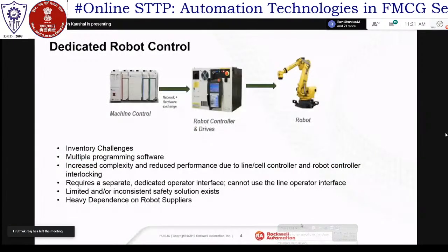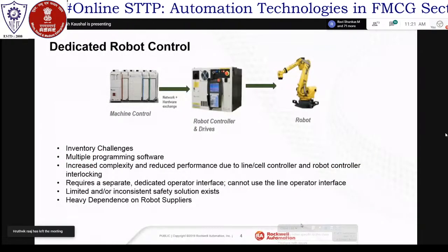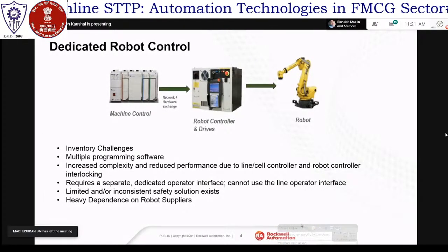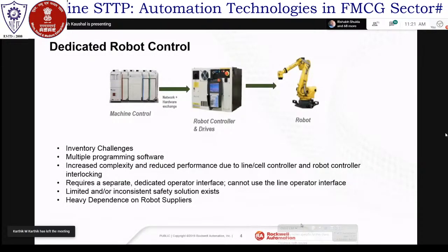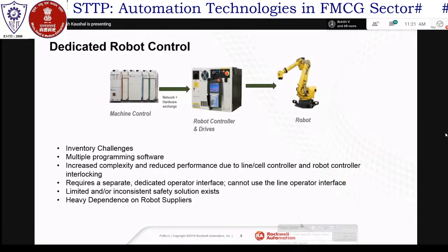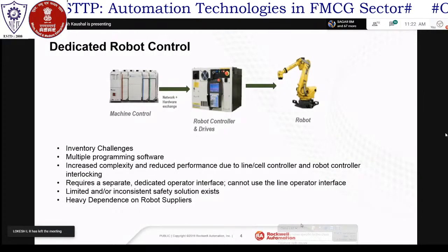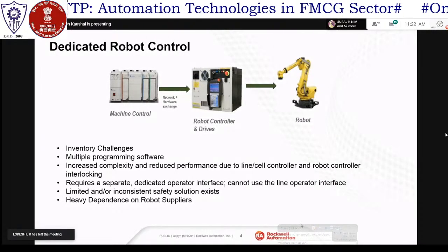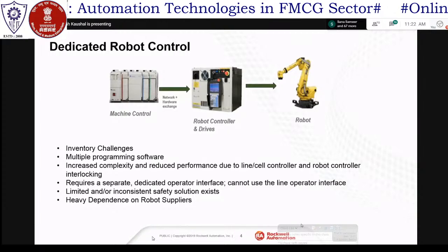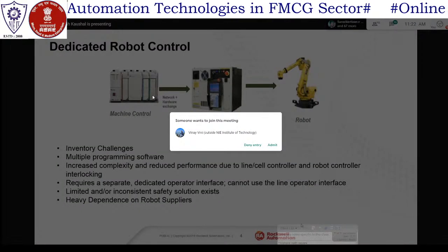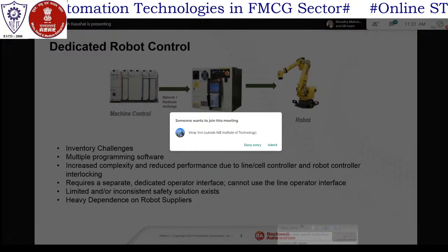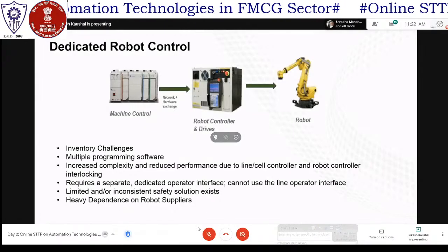So the first I'm going to talk about is robotics. There are a variety of robots which are used out on the floor, and the way of using them is that they typically come with a dedicated robot controller, and hence you need to have skilled manpower on your shop floor which understands how these robots are to be programmed, how they are to be deployed in the field, right? As well as the machines are typically controlled in a skid solution using a PLC, and typically there's a lot of network exchange and hardware interlocking that happens between a traditional robot control and a machine controller.